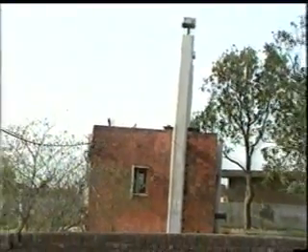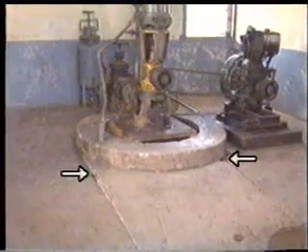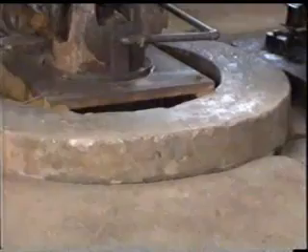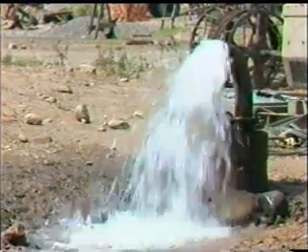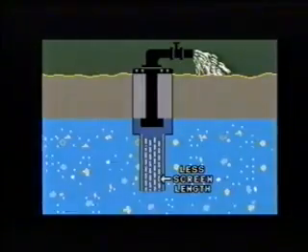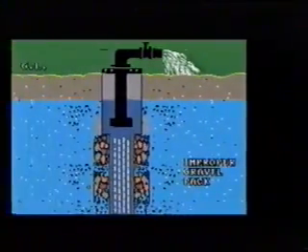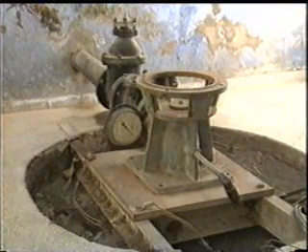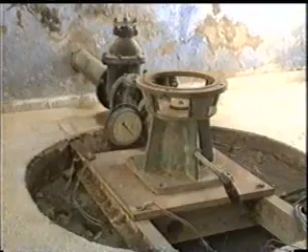Settlement of land surface around a well, cracking and settlement of pump pads and foundation are indicative of settlement of well structure. This may be due to excessive pumping or usually poor well design and construction. Such a well should be shut down or can be used temporarily by welding I-beams.